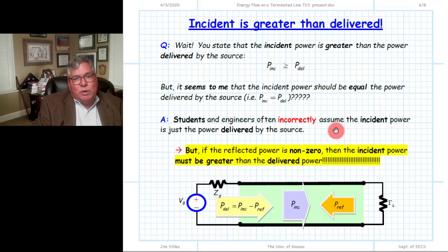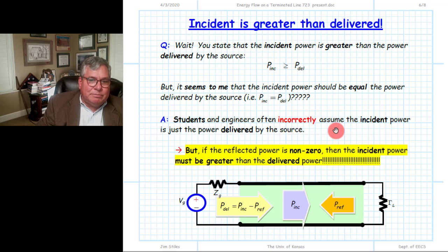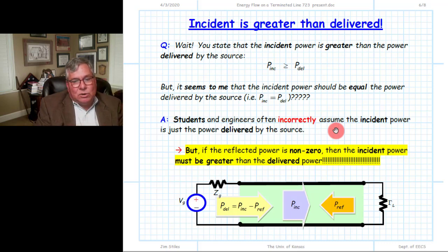Again, that plus wave propagating from the source down to the load, as we tried to show in the analysis of the boundary condition, has two terms. One term is dependent on the source, but the other is dependent on the interaction of the reflected wave with the source itself. The reflected wave effectively gets reflected again from the source. And so there are two components to that plus wave, and the source is only one of them. So bear that in mind. And the math shows that clearly.